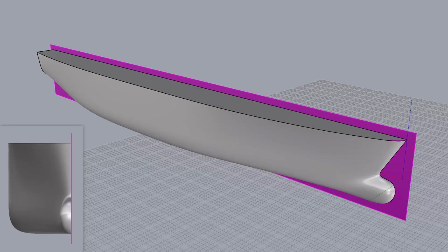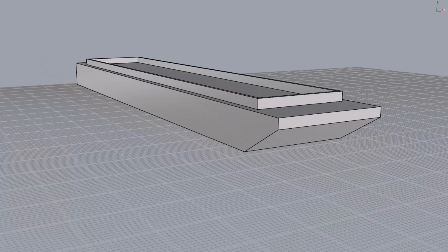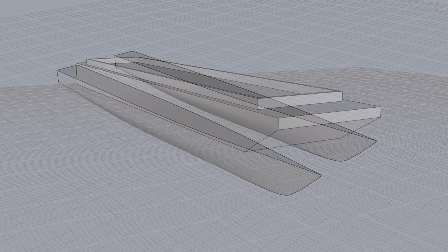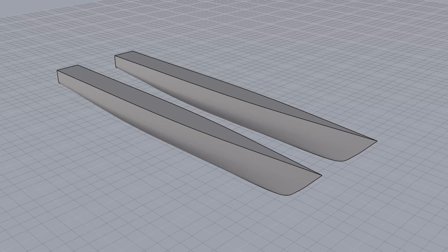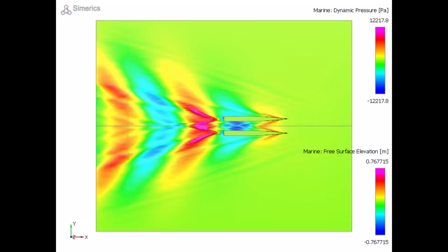Before using Orca 3D's Holtrop analysis tool, make sure you're familiar with the Holtrop method's limits. In addition to these, your model must be a symmetrical monohull, with the center plane at 0 in the transverse direction. If your vessel does not fit within the Holtrop method's parameter limits, is asymmetrical, or is a multi-hull, consider instead using Orca 3D Marine CFD. Simulation can provide highly accurate predictions for complex model shapes.